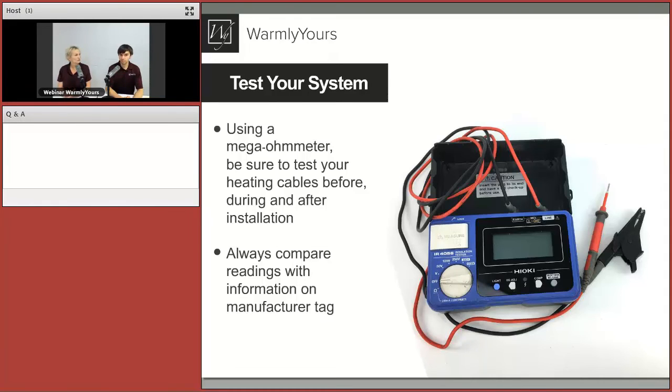One of the things that we should say though is for the constant wattage, it's not much of a test. You can really just plug it in and you can feel that the cable will warm up. If it's warming up, it's working. You can always just do a very basic continuity or ohm test on the plug, just like you would do on any other resistive heating appliances.